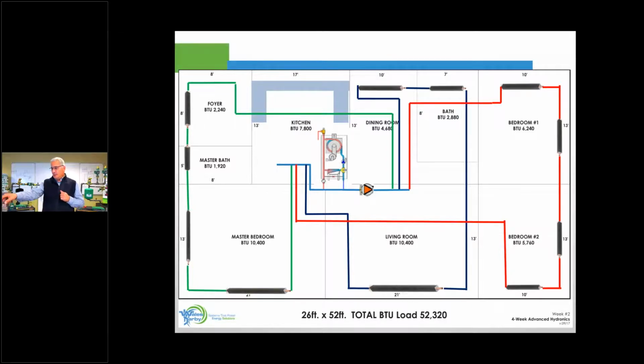Take that green loop, my guesstimation, just kind of get an idea. You can see the numbers for the walls and everything. Back to the boiler side at about 103 feet, and if I plug that in, 103 times 1.5 times 0.04, 6.18 feet of head. Again, we could call that 6 feet of head.